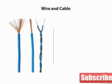Wire is by far the most important common component in electrical circuits, so much so that it is taken for granted. It is very important, however, that the right type of wire be selected for each circuit and circuit element. Wire is a conductor, usually copper, and is usually covered by an insulator, most often plastic, rubber, or lacquer. It is either solid or stranded.